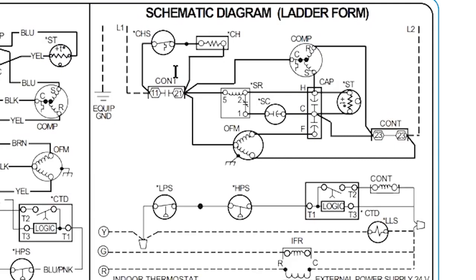These schematics are all designed to be read from left to right, like reading a book. So this is the permanent connection. And then this part here is the part that opens if it slides up and closes if it slides down, like it is right now. And so it's normally closed, open on rise, which means if the temperature increases, it's going to open the circuit and shut off this doohickey here.